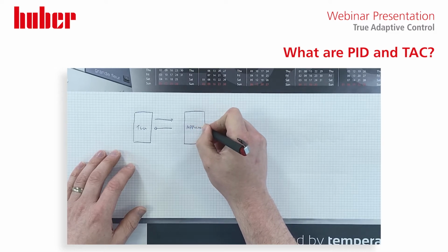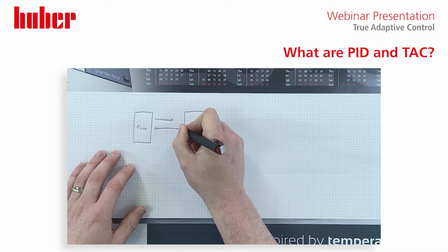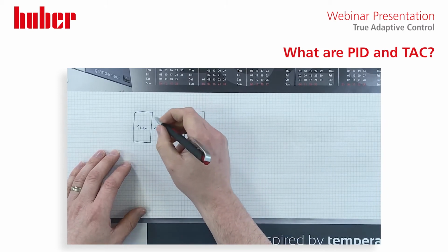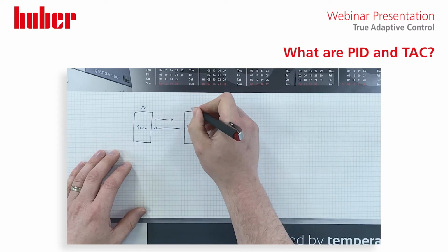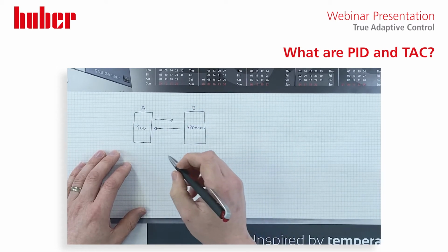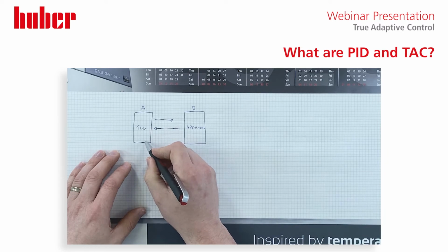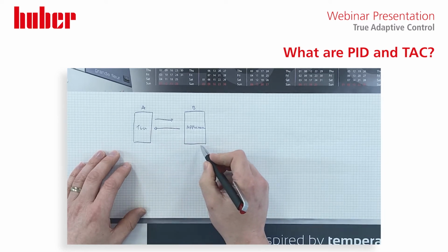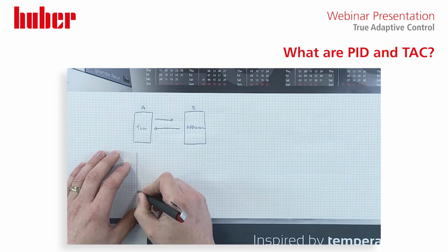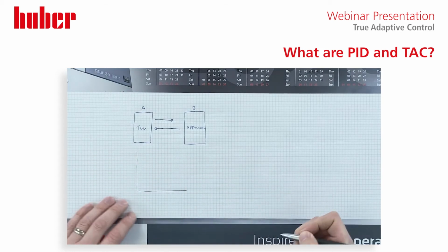But a key factor here, with regards to overshooting and undershooting, is the distance between the TCU and the application. When the TCU sends a packet of energy, how long does it take to reach the application? And will that cause your temperature control to overshoot or undershoot?